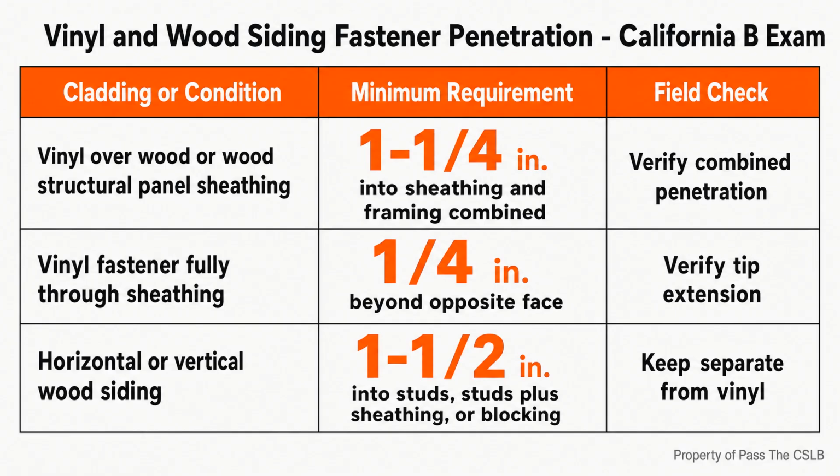Wood siding, fiber cement siding, vinyl siding, and other systems do not share one universal butt joint gap or treatment. Some details rely on joint flashing, some on trim or accessories, and some on product-specific spacing. I verify the selected product, the approved installation instructions, the plans, and any applicable code requirement instead of applying a remembered gap from a different material. That is the main distinction I want you to keep.